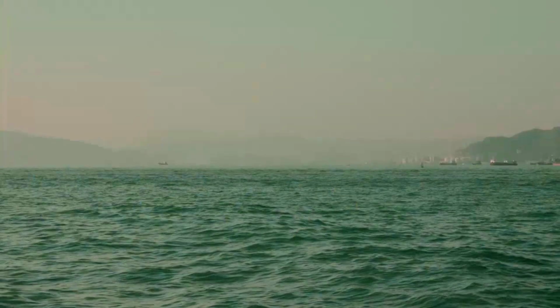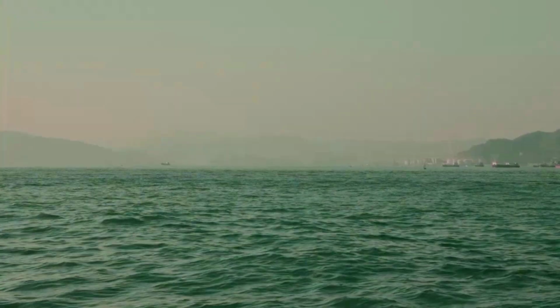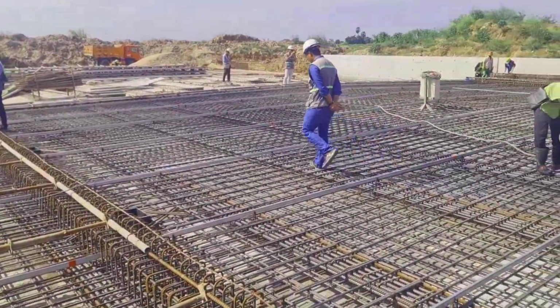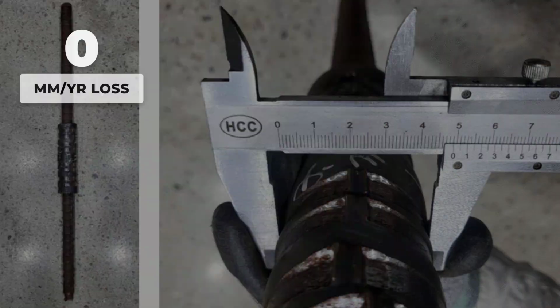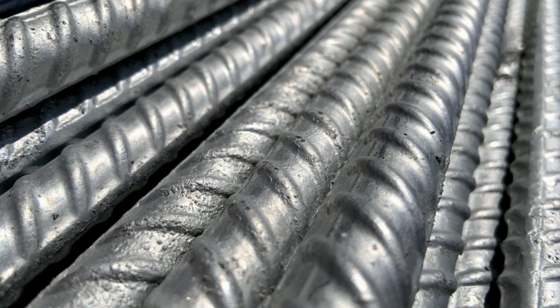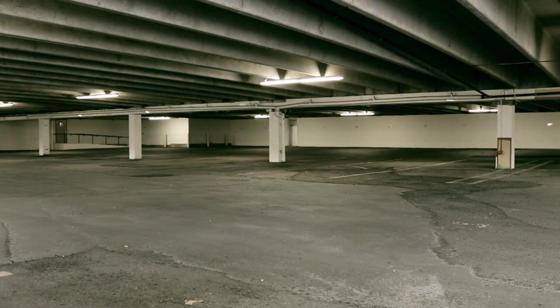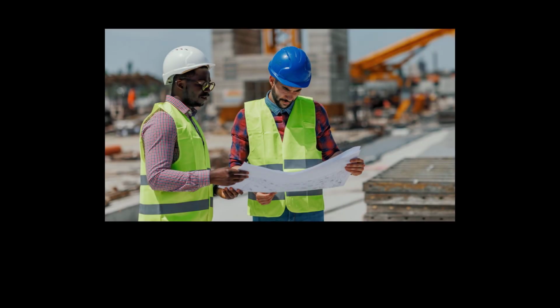These cracks, though small, create a pathway for water to reach the steel reinforcement inside the slab. In coastal cities like Hong Kong, chloride-laden air accelerates corrosion, with public works data recording rebar loss at a rate of 0.02 millimeters per year. Over a decade, this can reduce the cross-sectional area of the steel by nearly a fifth, quietly undermining the slab's strength.